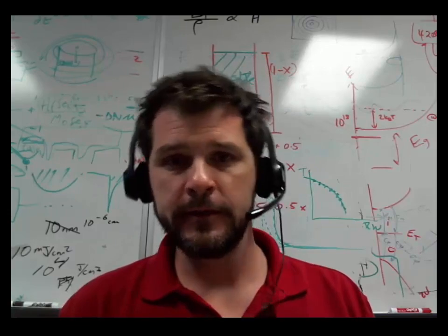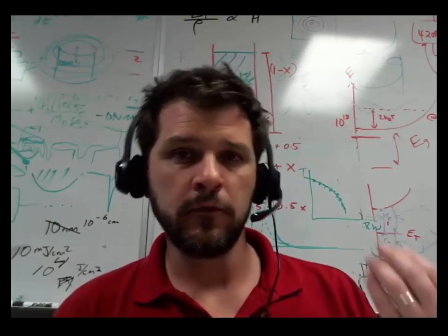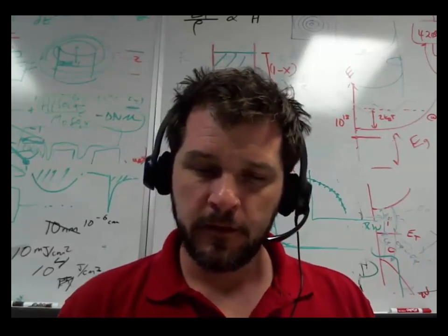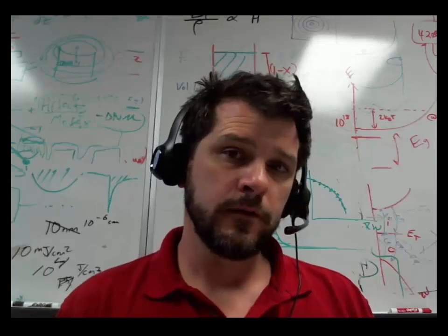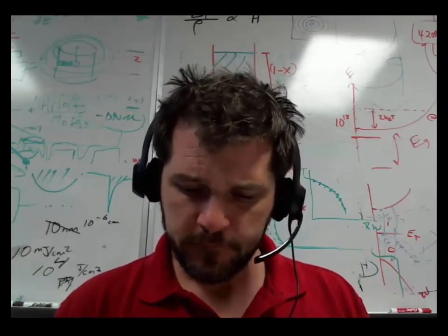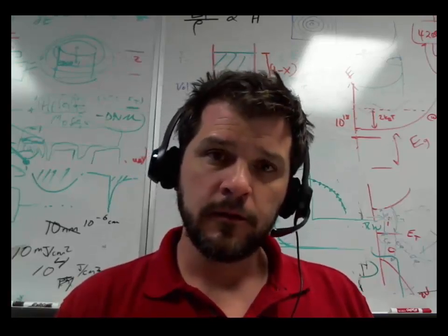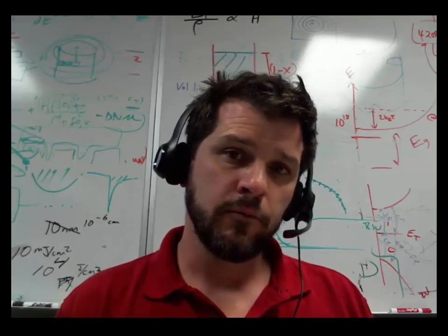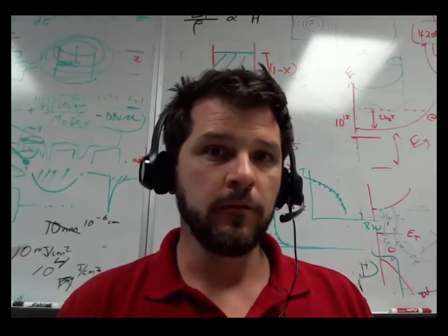We've also added this new concept of saturation, where the source drain current rolls over and becomes constant because of the pinch off in the channel. Then we've looked at the transconductance, also the so-called subthreshold swing, and then lastly looked at the effects of using the fourth terminal, the backside or body voltage that you can apply to the wafer itself to help the gate do its job.